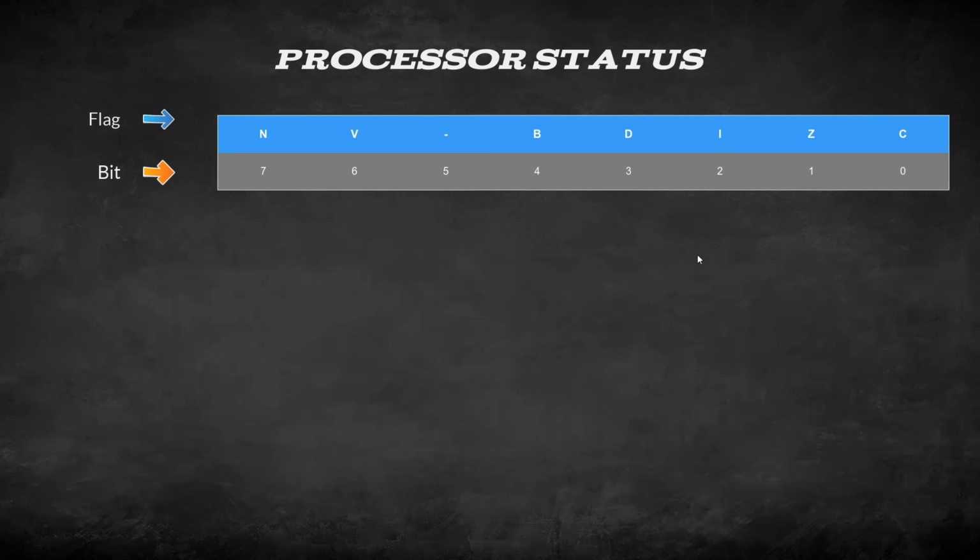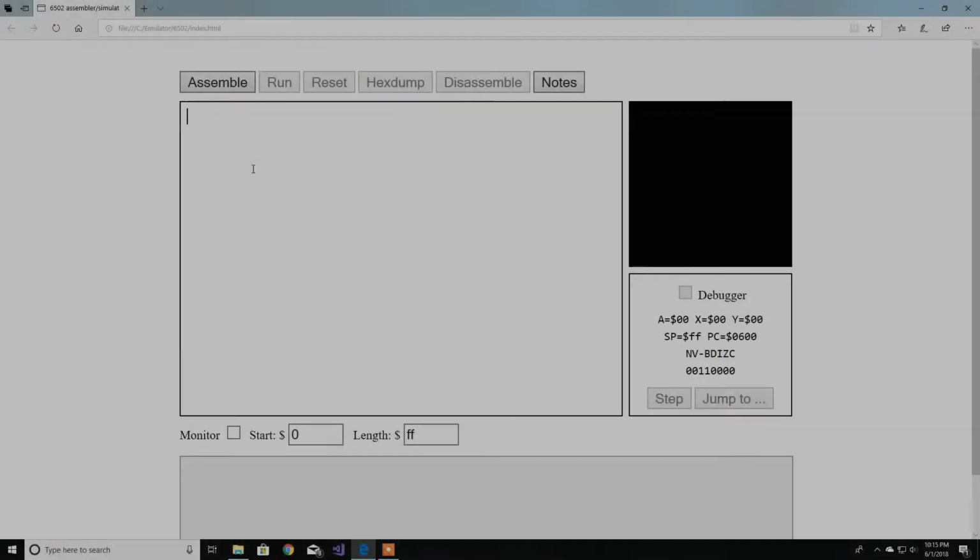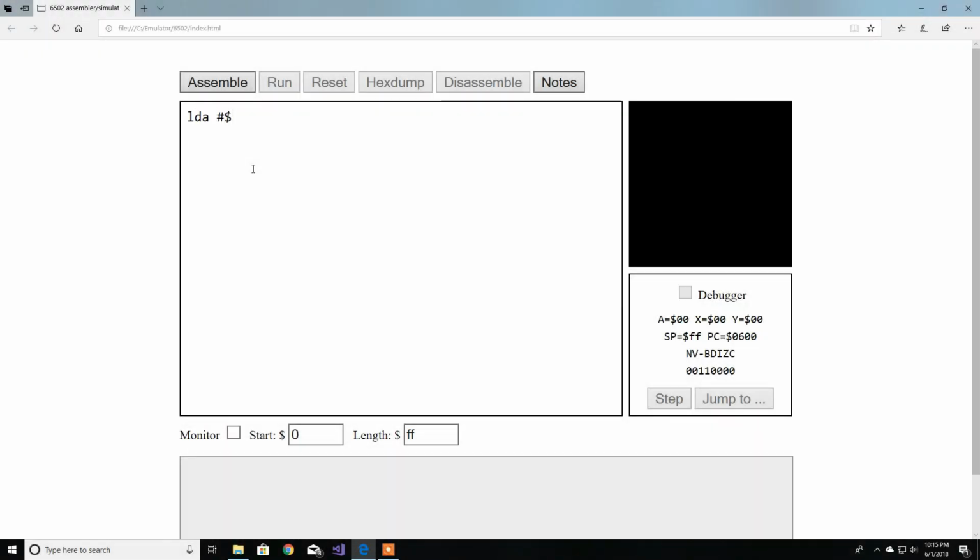The next flag is the Z, which is the zero flag. Put over here. Z equals the zero flag. And the zero flag is set if the result of the last operation that you used is 0. So let me show you what that is. It's pretty simple. Okay, so let's do something really simple and fast. So let's put the 80 hex, which is this value.